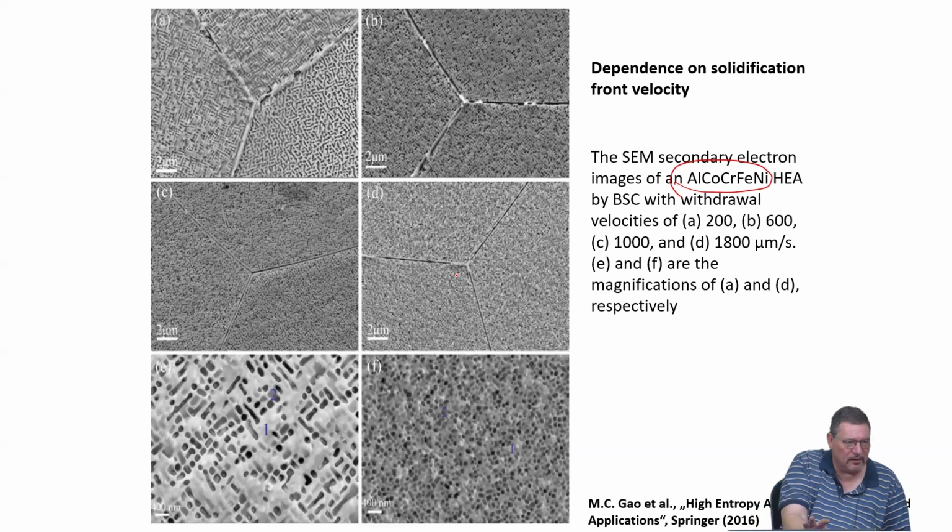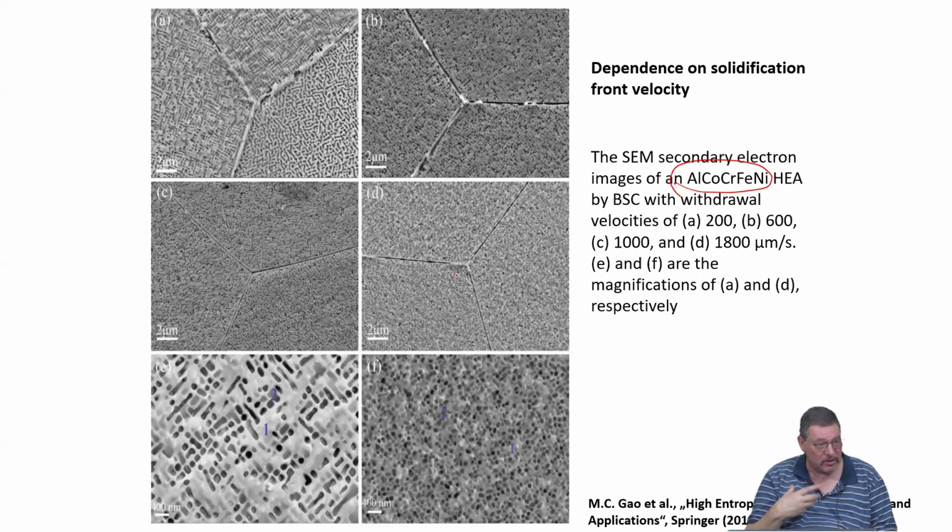In alloys made by this, you don't need a deformation process in post-processing, because then you would destroy the microstructure, right? So you have already used a process that makes an optimized microstructure, and it gives you control over the resulting microstructures.